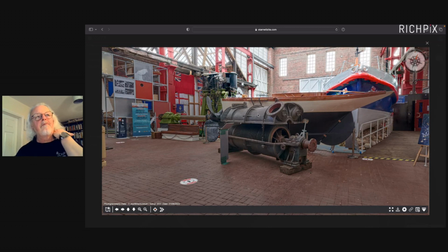Decommissioning is largely about trying to figure out what you've got. It's a process in the nuclear industry they call characterization. There's so much stuff in a nuclear power station that's being decommissioned. There are lots of different routes depending on the contamination level, what's in it, how heavy it is, and the material. Everything in a nuclear power plant has to go through a process called characterization, so it's given its own unique waste disposal process.